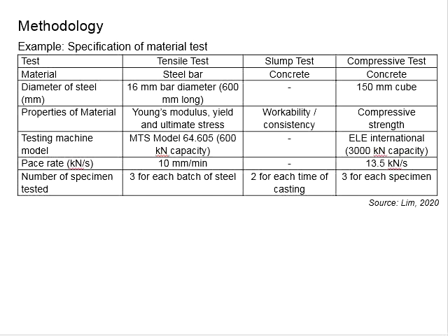Let's say now you estimate the tensile capacity of Y16 steel bar having the Fy of 500 megapascal is somewhere around 135 kilonewton. You will need to choose the testing machine with a capacity at least more than 135 kilonewton. It is so that the machine can actually break the sample and acquire the tensile capacity of the sample.